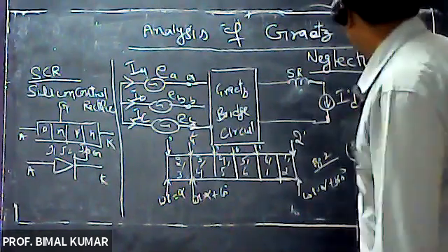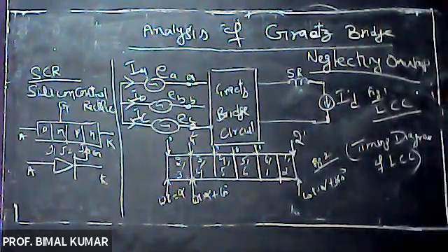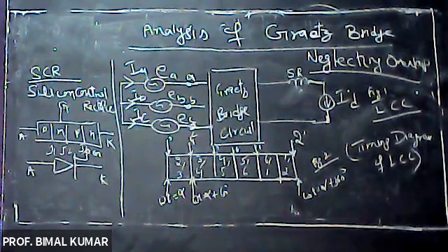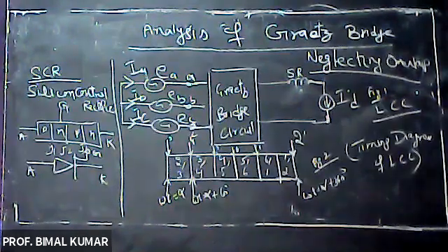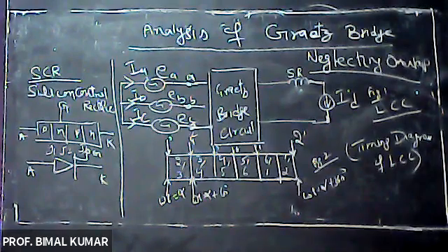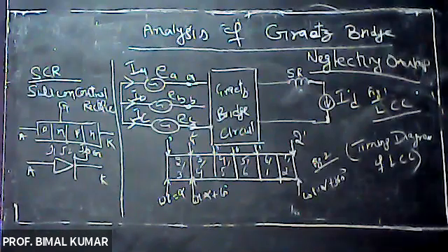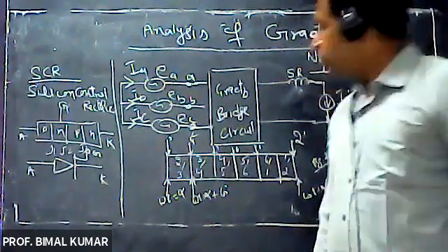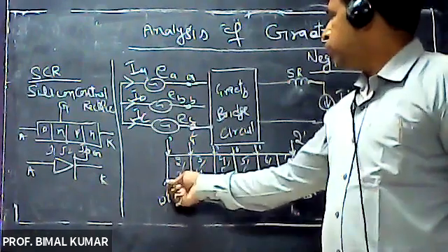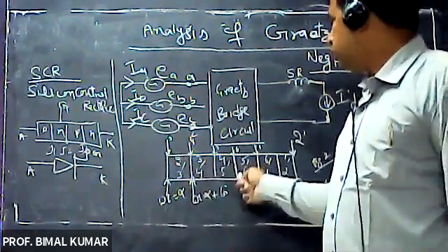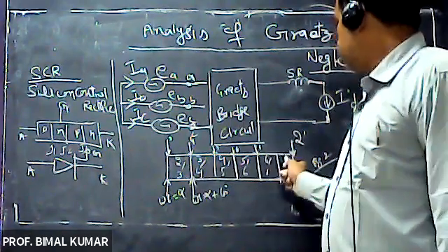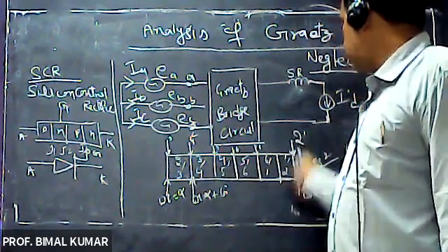Right. So during each interval, the number of thyristors conducting is equal to 2. During each interval, 2 SCRs or thyristors will conduct. The rest, 4, are in the silent condition. And the duration of the conduction is 60°. 0 to 60, 120, 180, 240, then 300 and 360.